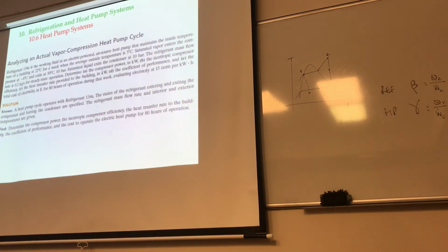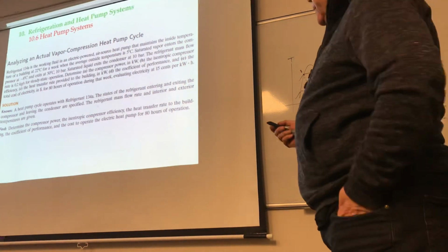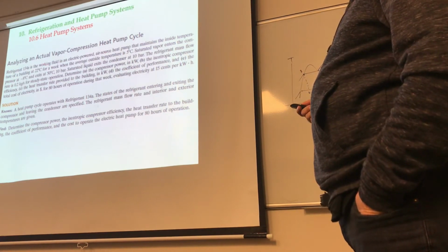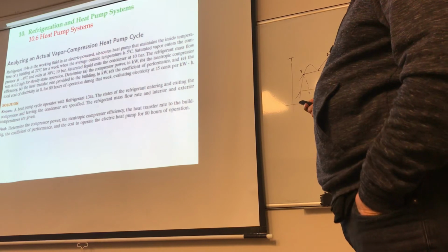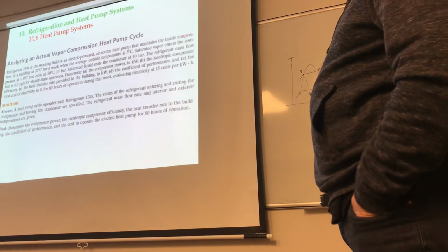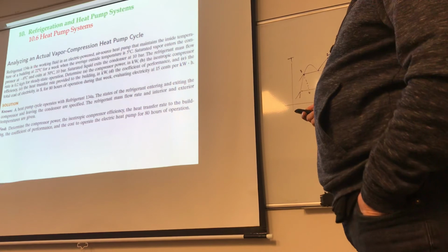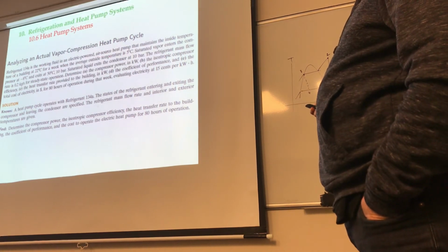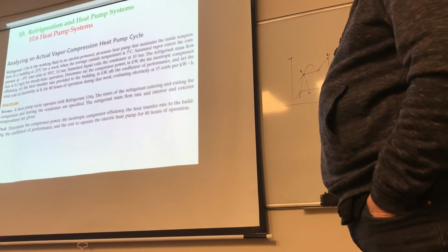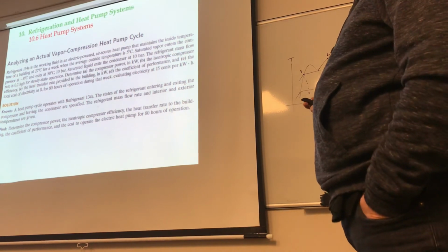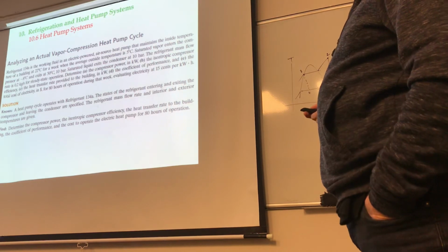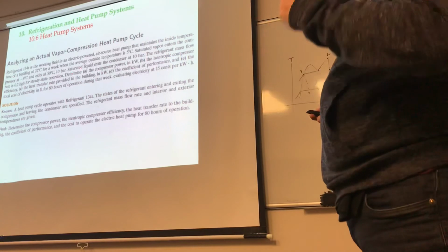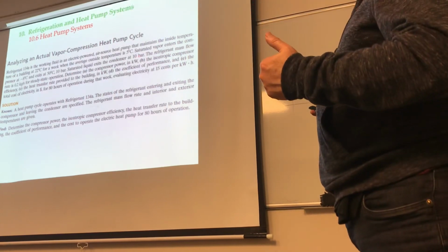It's a refrigerant 134a working fluid, electric power, air source heat pump that maintains the inside temperature of a building at 22 degrees for a week when the average outside temperature is 5 degrees, which is kind of what a heat pump does, right? Saturated vapor enters the compressor at -8, exits at 50, and then saturated liquid exits the condenser at 10 bar.